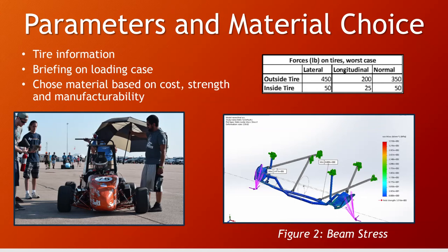The car used Hoosier LC0 compound tires. A previous team member analyzed data from Calspan Tire Testing Consortium and found the peak coefficient of friction for these tires. The peak coefficient of friction that our member arrived at was 1.6 for the chosen tire. Specifically, this is the maximum friction available for all of the tire's dynamic behavior at any point.